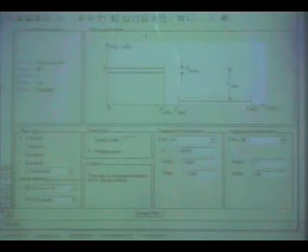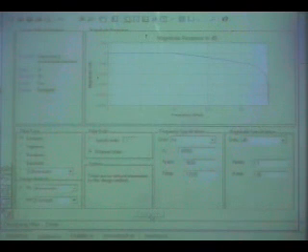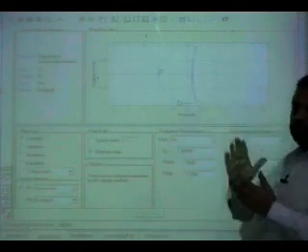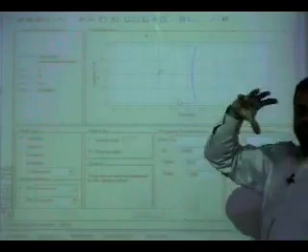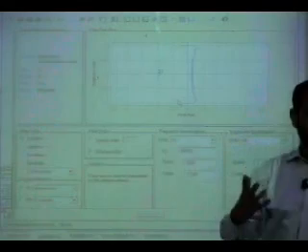So Butterworth, you say Butterworth, and then you say design filter. Okay, so Butterworth is a very smooth filter. The interesting thing is looking at this: it says a 31st order filter for these specifications, but I really am expecting these poles to be on a curve, because remember in S domain they were on the half of the circle of radius omega c.